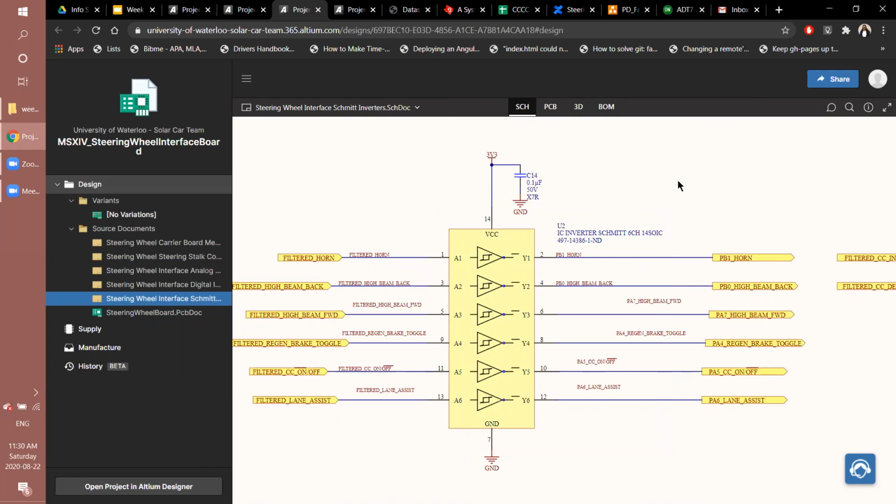Because of that, if you just had a normal switch going into a controller board, you would be triggering a high and a low a lot of times when you clearly want a high value. So what a Schmitt trigger will do is after you pass that high value, it will lower the threshold from 3 volts in this case to something lower, maybe like 2.6, before you have a logic low.